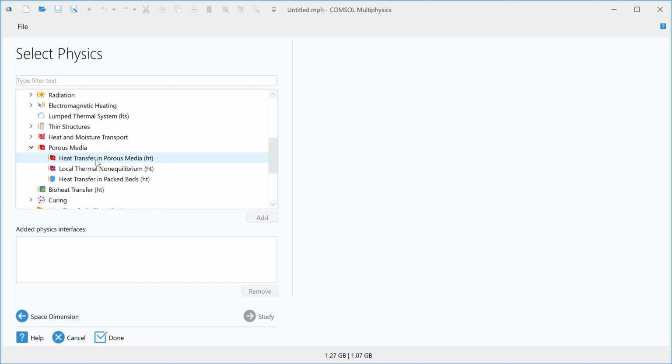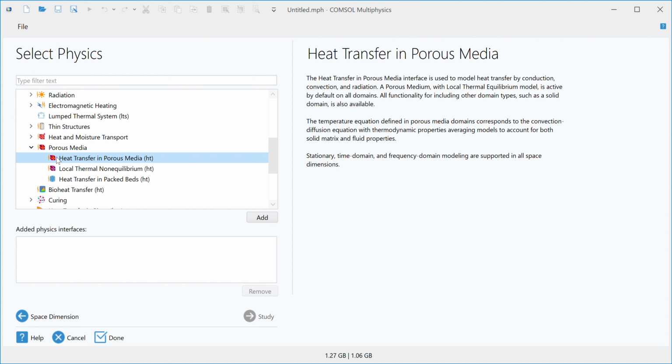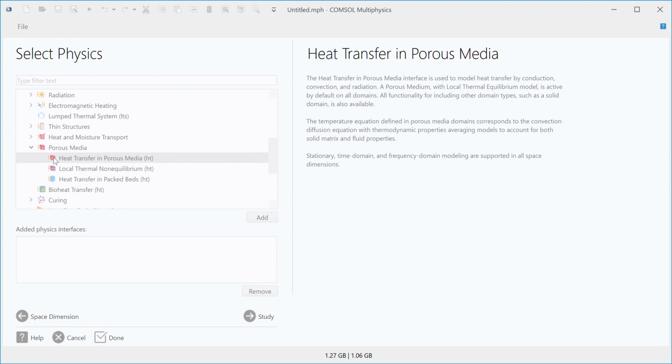So this ground will be treated as porous media, and our existing structure will also be considered as a porous media, but we will consider the porosity of the structure as zero. As we know, this concrete doesn't have that much water flow in between, but to have some relations we have to consider this as a porous media.